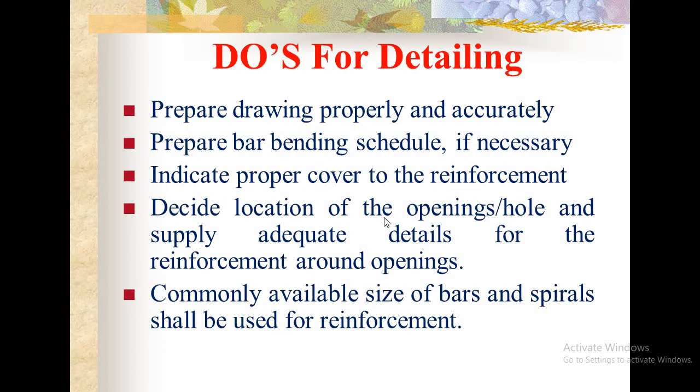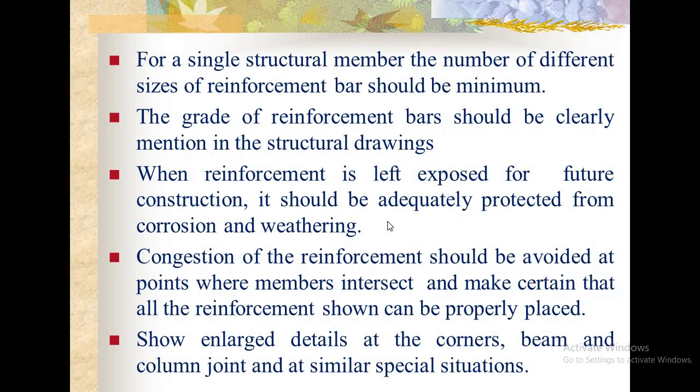Commonly available size of bars and spirals shall be used for the reinforcement. For single structural member, the number of different size of the reinforcement bar should be minimum. The grade of reinforcement bar should be clearly mentioned in the structural drawing.